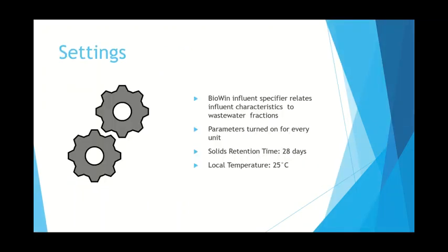To set up this BioWin model, the influent concentrations are put into an influent specifier model off of the Valrico plant to give the appropriate wastewater fractions related to our data. The solid retention time for the sludge is set to 28 days. This means that after 28 days, the sludge is dumped and newer sludge is allowed to accumulate and run through the system. For the units, all the parameters such as kinetic, aeration, and diffusion, and the temperature are turned on, and the temperatures are set at 25 degrees Celsius.